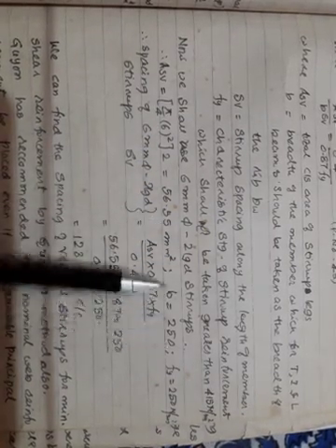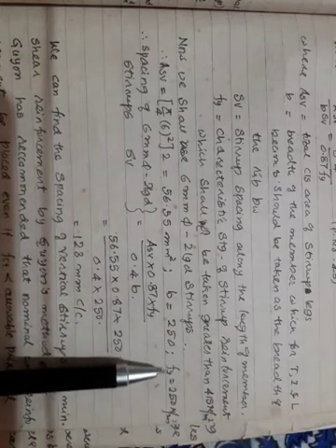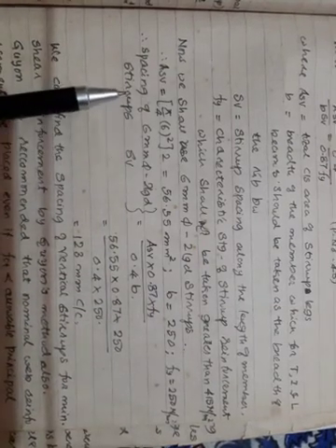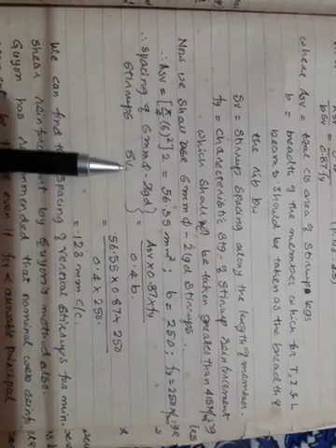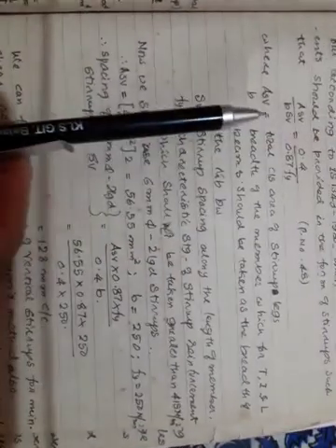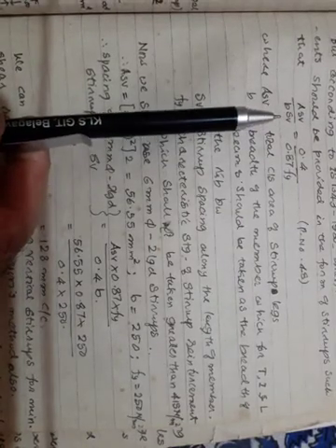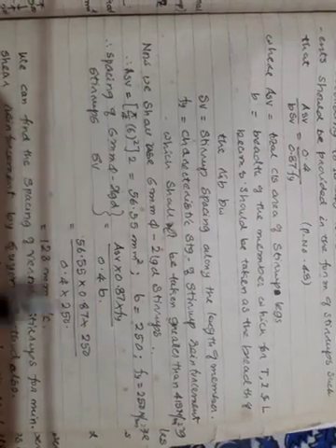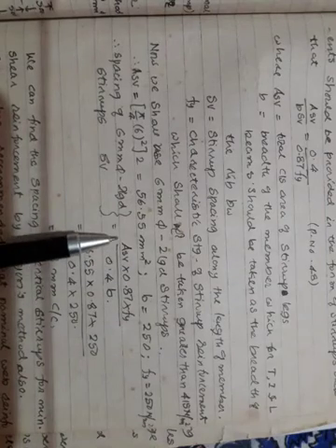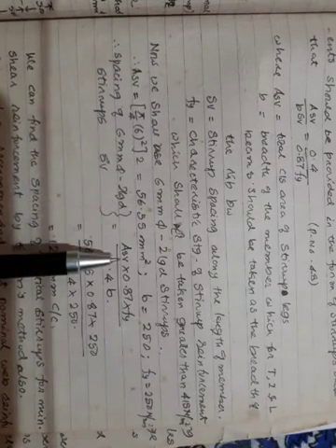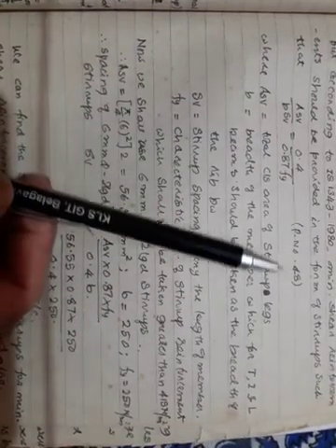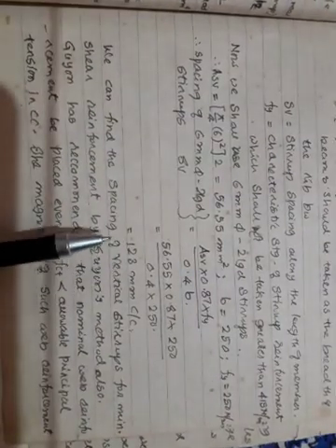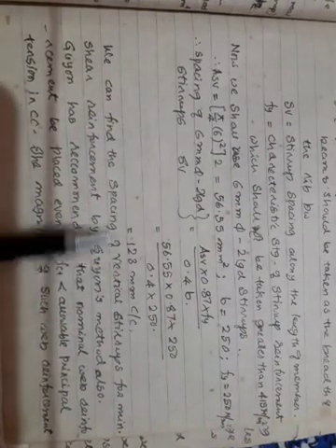Breadth of the beam is 250 mm and Fy value is now 250. So I can easily calculate the spacing of 6 mm 5 two-legged vertical stirrups. In this equation, spacing can now be easily calculated. Rearrange the terms and you will get this equation: spacing SV is equal to this much. But you need not remember this equation. It is there on page number 48. So now spacing works out to be 128 mm center to center.